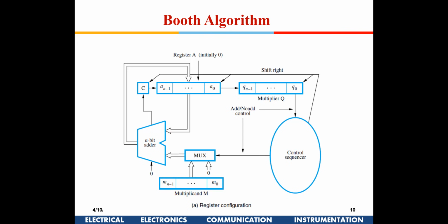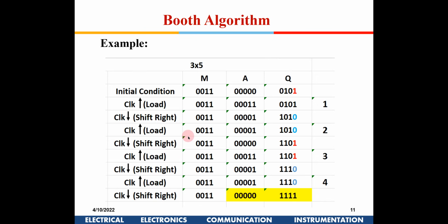For A, because this is parallel addition, right? You have this entire data available here, the entire bit available here. This is a combinational block. So the moment this data is placed here, it will give the output out here. This is not a sequential adder. It is just a combinational adder. Is it okay? Okay.